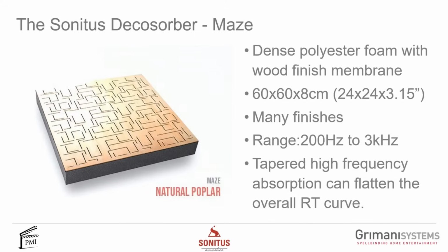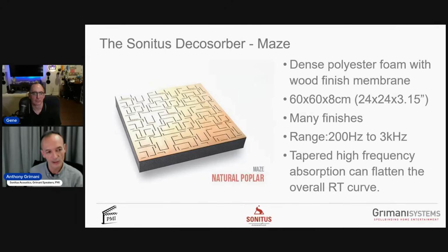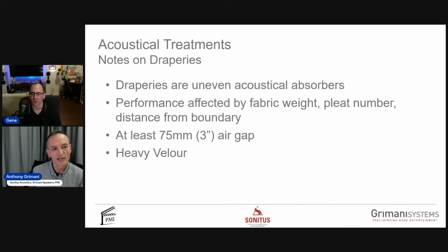So it does let some sound through at the low mids and the bass. The top layer is tympanic, so it absorbs bass better than a regular frictional absorber, and you include those in your acoustic treatment package, and those things take care of the reflection energy below 300 or 400 hertz. And that's a cool way to treat your mid bass. It looks like a board cube.